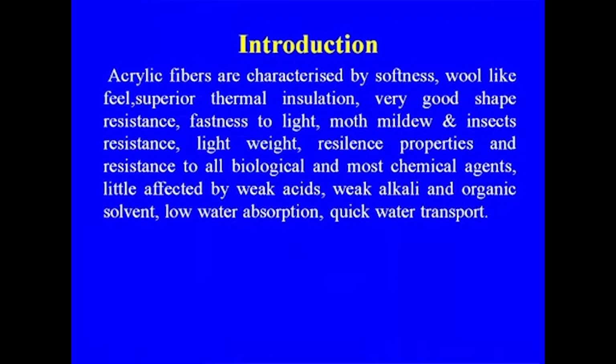properties required for carpet, which earlier was normally woolen material that was being used. And another property is lightweight, resilience, resistance to all biological and most chemical agents, little affected by weak acids, weak alkali and organic solvents, low water absorption, quick water transport, meaning the drying is much faster in the case of acrylic fiber, and this is the reason why